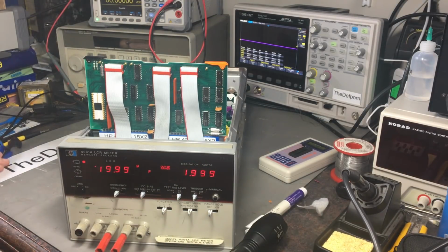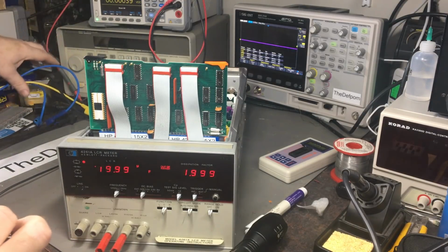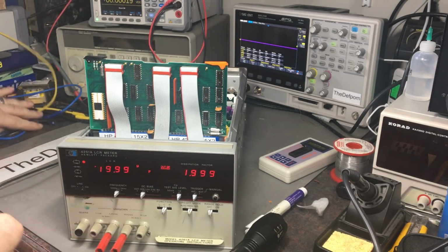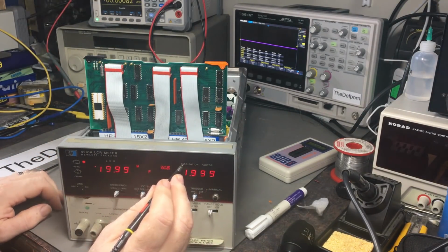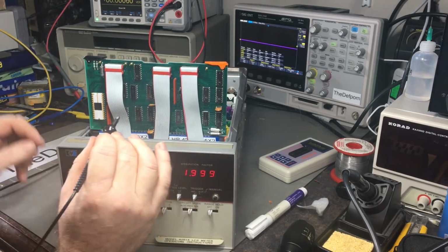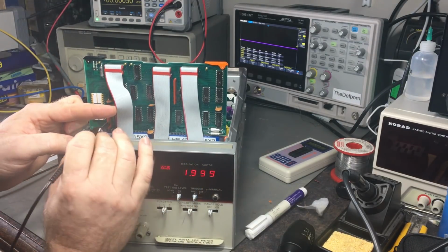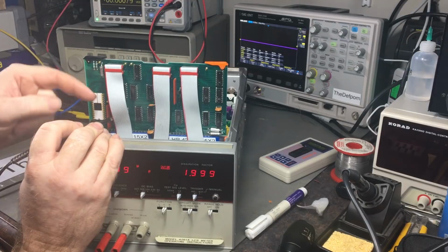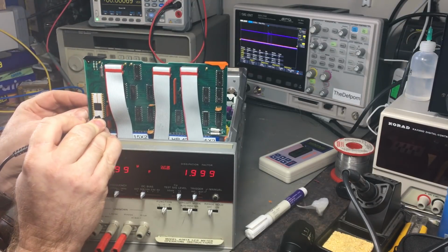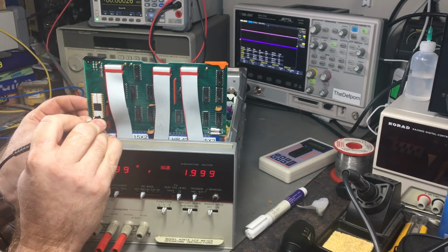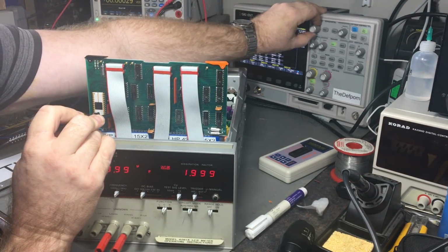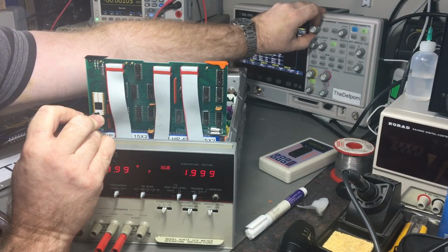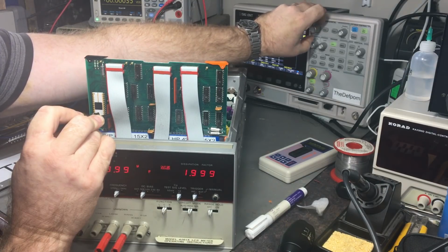So now I've got to check on these pins to see what's going on. Oh man, I've got to tidy up this desk again. Right, so pin 4 of U10. Where's U10? Here's 11. So that's probably 10 under there. Yes, it is. So pin 4 of U10, which is over here. Almost like 7 to 9, isn't it? So there's something going on there. Let's bring that down so I can see.